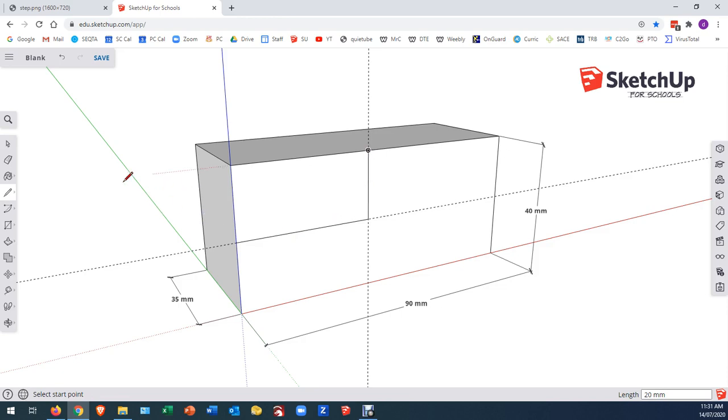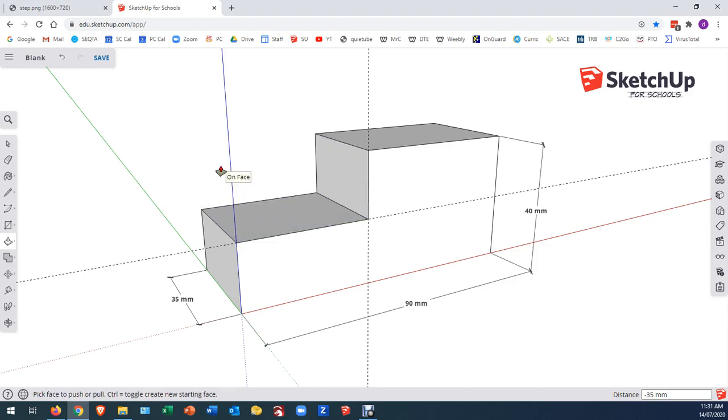So there I have what is now two separate surfaces. I've split this one big surface into two smaller ones. That's what I want to have remaining. That's what I want to take away. And the way I do that is by using the push-pull tool. I click on there and I push away, and I keep pushing until it disappears. And there's the shape that you need.